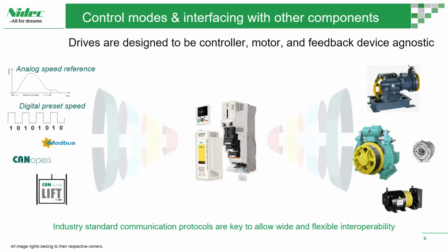So while there might be different control methods, starting from analog speed reference, where basically a controller gives constant speed commands to the drive, and the drive is really just acting as sort of an amplifier and just delivering the necessary speed and torque on the motor, but the controller is fully in charge, to then moving on to digital preset speed, where there are multiple preset speeds set up in the drive, and the controller is just choosing between speed 1, speed 2, down to creep speed, and then obviously 0 speed.